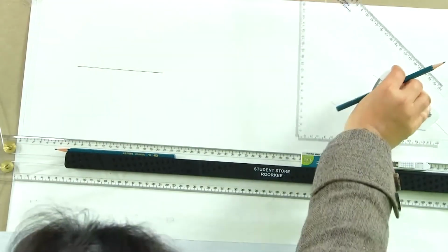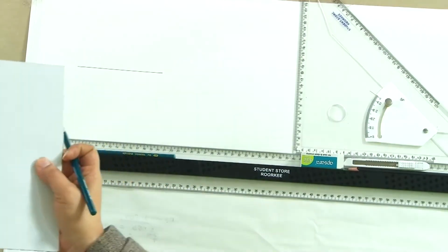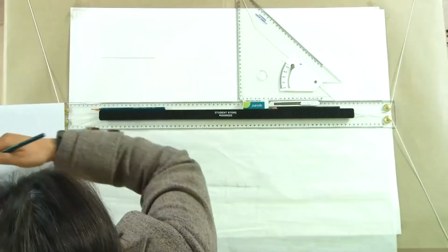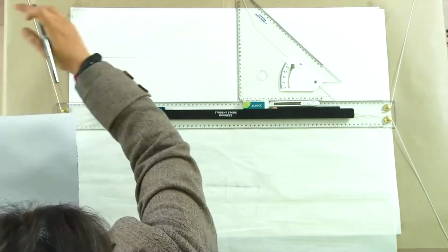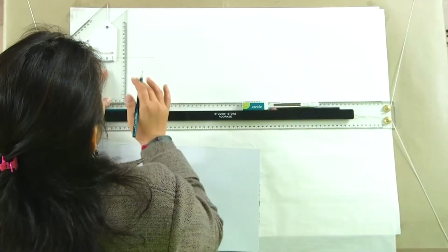Now, visualize it again. We have this point here, which is at 5 centimeters from the VP. So, when we see it from the plan, we will see that the point is at 5 centimeters from this reference line, because this plane will appear to be a single line. So, we will have 5 centimeters in front of the VP.